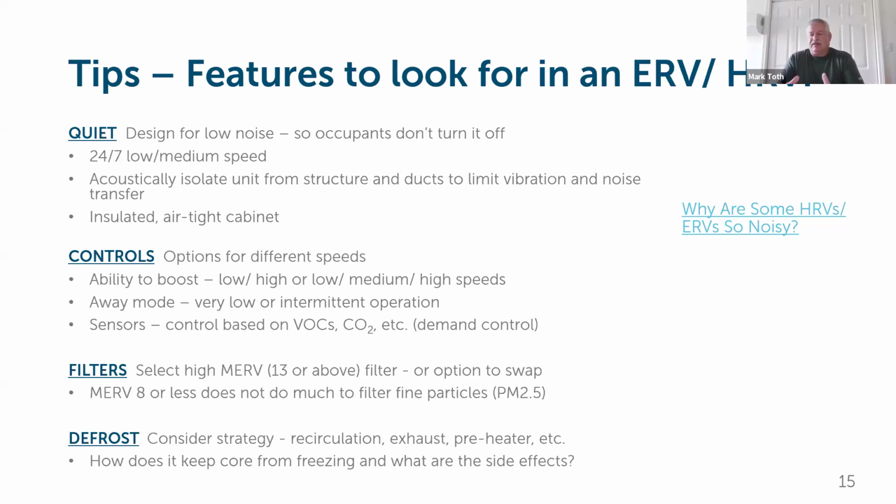And this drain thing is a big deal, because when you're building a new house and you're installing an ERV or an HRV, and at the last minute you find that you have to have a drain line from it, and there's no drain in your basement where you're going to put it, that becomes quite an issue sometimes. So just take everything into consideration when you're looking at the units. How quiet is it? How are you going to control it? The filter options and the defrost. So look at the whole picture before you make your decision. So go ahead.